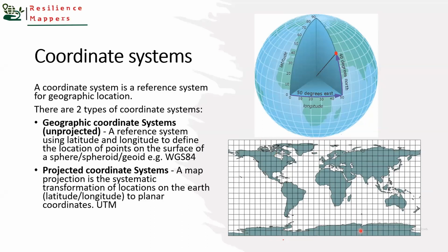which is not the case. So these projection systems, however much we use them, have areas where they are best applied, and in some areas they don't work. Each country may have its own projection system that it decides to use because it's the best for that country. So if you're working in the USA, you can't use the coordinate system that we are using in Uganda, because it will have different errors, maybe more errors than for us here. For us, we decided to use Arc 1960 UTM 36 North, because it's what at least minimizes the errors.